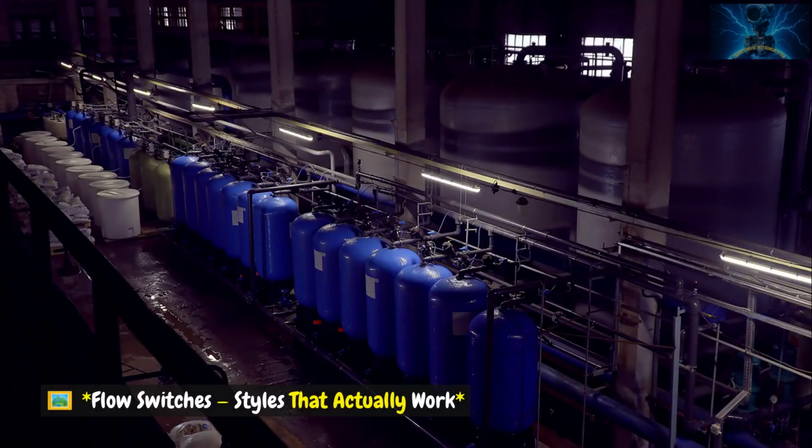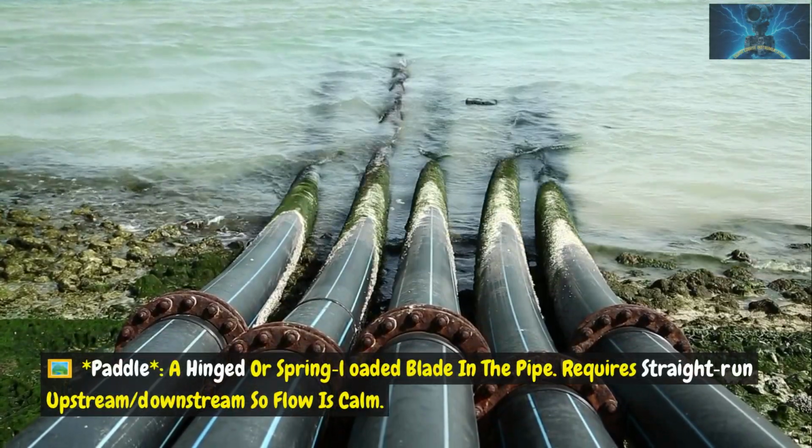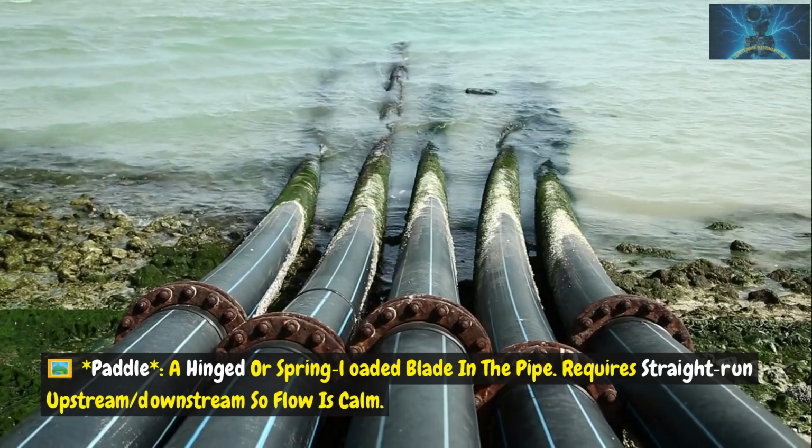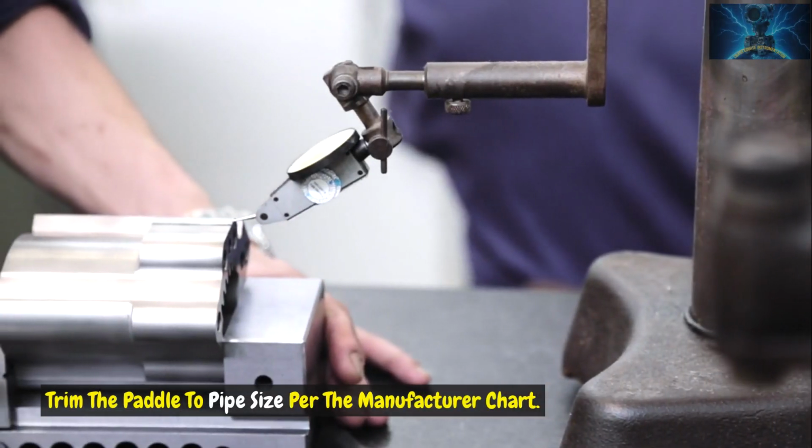Flow switches, styles that actually work. Paddle: a hinged or spring-loaded blade in the pipe. Requires straight run upstream and downstream so flow is calm. Trim the paddle to pipe size per the manufacturer chart.